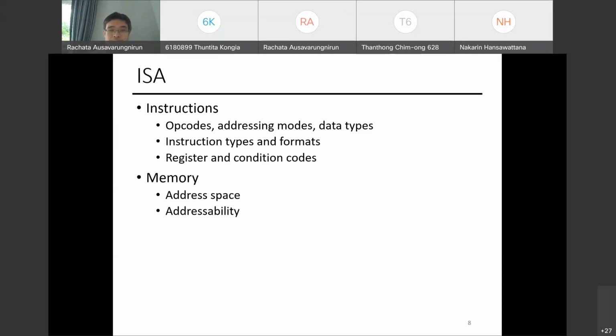Addressability: do you want to access every single byte, every single 4 bytes? Alignment: are you allowing this weird 4-byte access, but on the third byte and on the second byte, instead of making sure everything is fully 4-byte aligned or 8-byte aligned, right? The ISA will tell that.